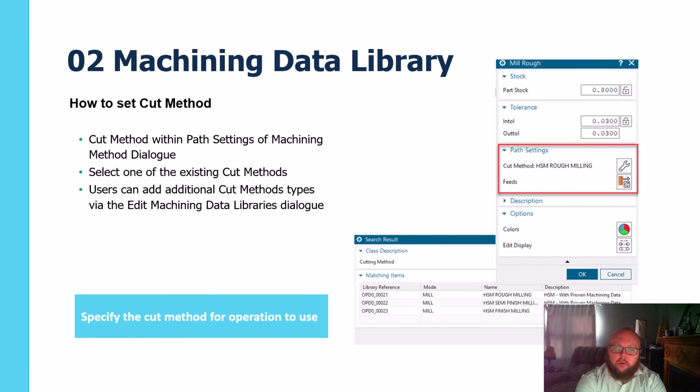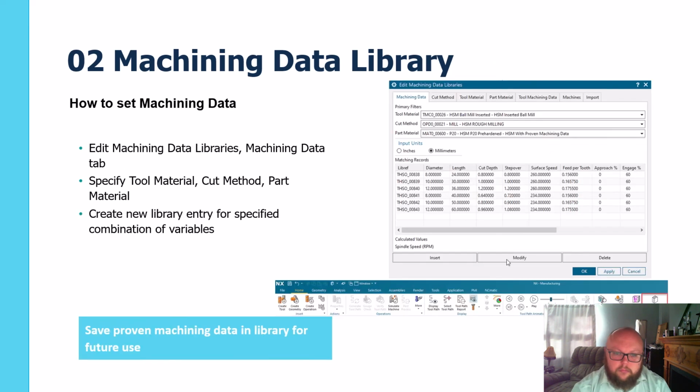Whether we're doing more of a conventional roughing strategy, slotting, things like that, versus a high-speed machining roughing method where we're going to be utilizing our adaptive cut patterns inside of NX. High spindle speeds, high feed rates, large depth of cuts, very small step overs, or our high feed milling where we're doing very low depth cuts but high width of cuts, typically used in hardened materials. So a number of different strategies, and we want to embed all that information in our libraries here.